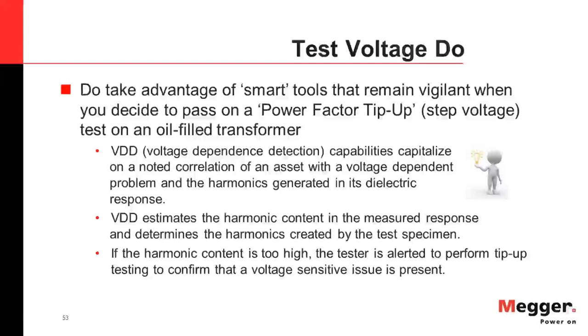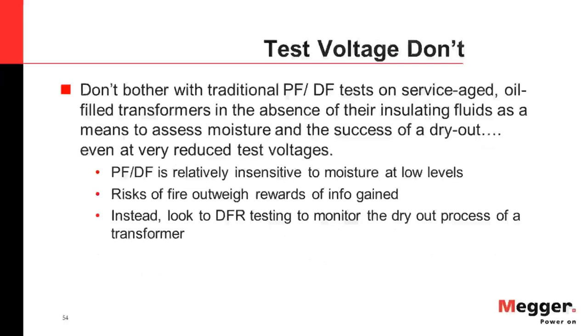And you're assuming if you're drying it out that you've got it to not crazy high levels to begin with. So in that case, the risk of a fire outweighs the rewards of any information that is going to be gained by this test. Instead, I would recommend looking to dielectric frequency response testing, which has turned out to be a really good way to monitor the dryout process of a transformer.